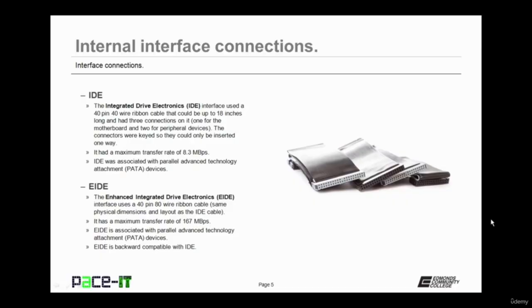Now the IDE had a maximum transfer rate of 8.3 megabytes per second. IDE is closely associated with the Parallel Advanced Technology Attachment Standard, the PATA standard. Well, we found out that IDE just wasn't quite enough, so they came up with EIDE, the Enhanced Integrated Drive Electronics Interface.